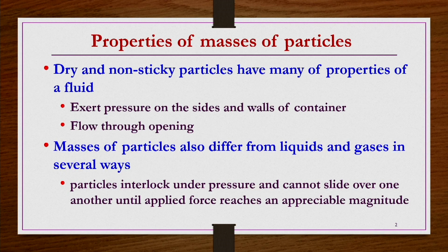If you apply pressure, the flow may be more comfortable, but in the case of solids, if you gradually increase the pressure, it is not necessary that the flowability of this material increases. That depends on the size of the grains that we are handling. Let us say you have very small size grains, then when you gradually increase the pressure, rather than increasing the flowability, the particles will become compact, a stronger packing will take place, and then the material may not flow through.